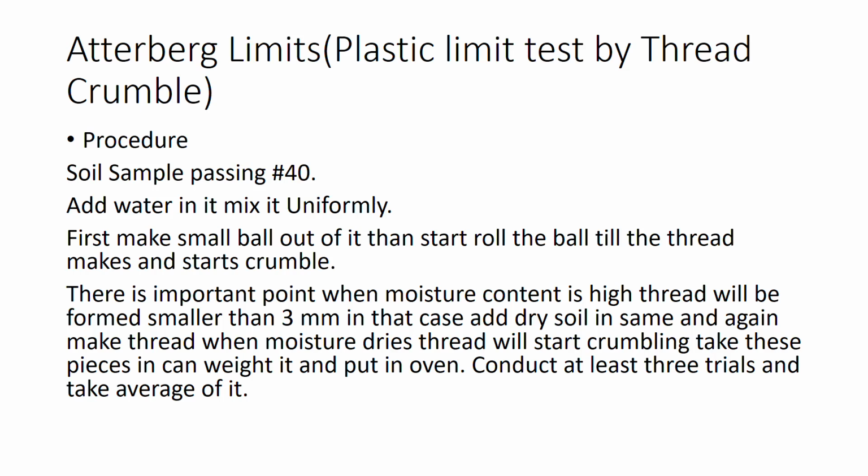You need to roll the thread back into the bowl, add some dry soil, and then again roll it into a thread. When the thread crumbles, you put the sample into the cans, note down the weights, and put it in the oven for the drying procedure.